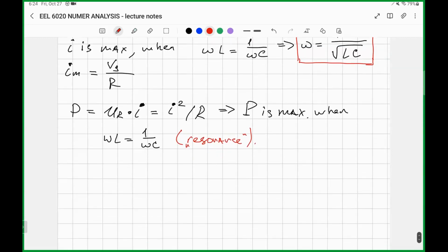And it is crucial that in such cases, or typically, we like to get rid of this reactive part of the impedance of the circuit to increase the efficiency of the circuit. And this is known as impedance matching.